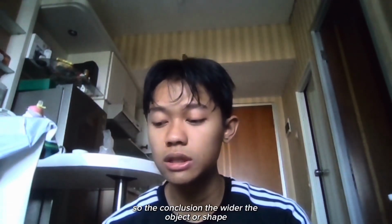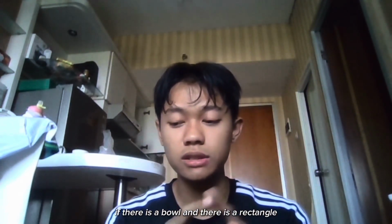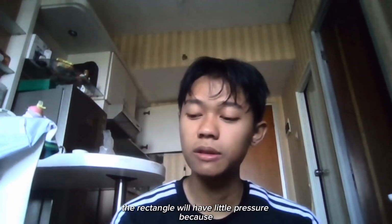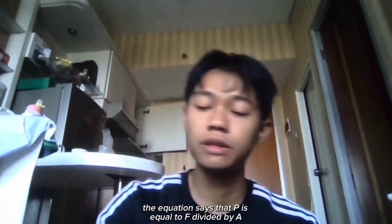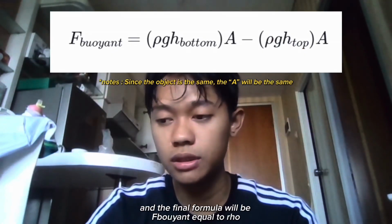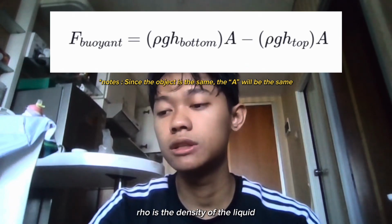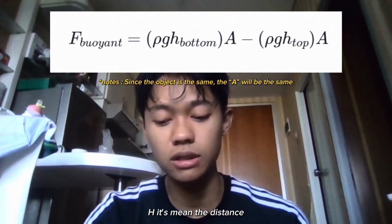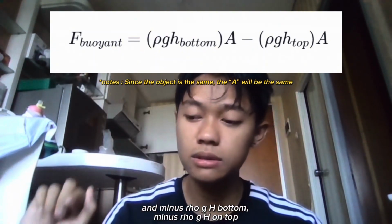So the conclusion: the wider the shape, if there is a ball and a rectangle, the rectangle will have little pressure because P is equal to F divided by A. And the final formula will be F buoyant equals rho, the density of the liquid, times g, gravity, times h, the distance, minus rho g h bottom minus rho g h top.